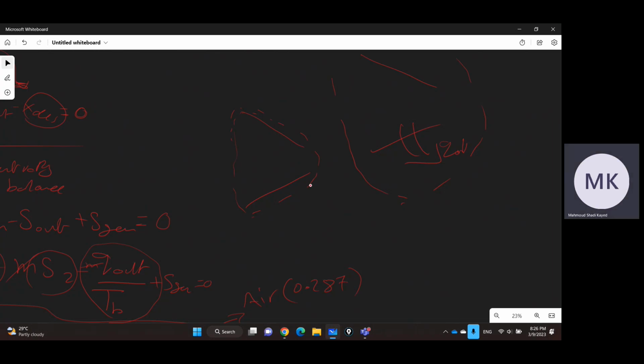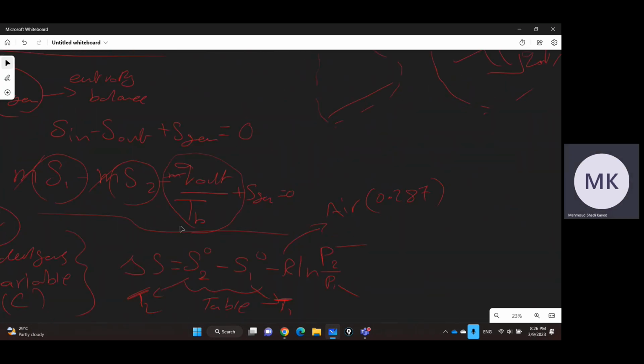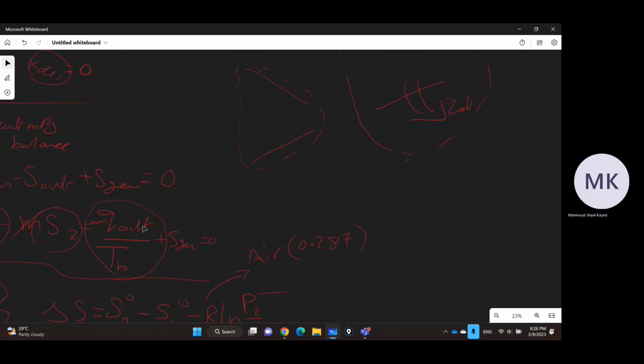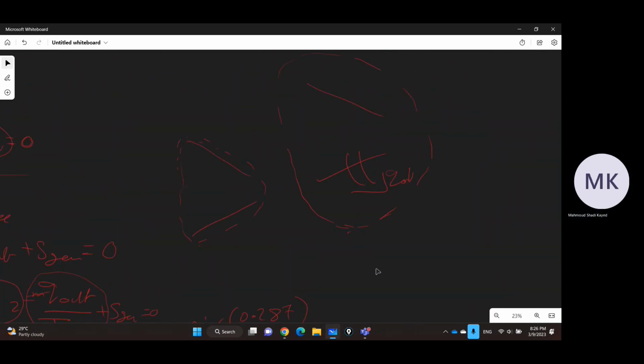But unlike the exergy formula, this term will not be zero, because we need to account for the heat transfer inside our system, which will be converted into entropy generated inside our boundary. So usually this method, the expansion of the boundary, is used to include the total entropy generated in the heat transfer process.